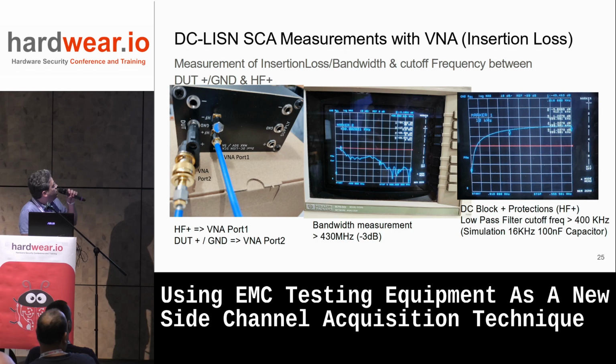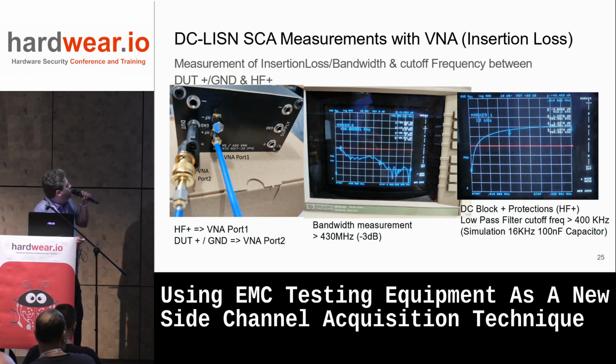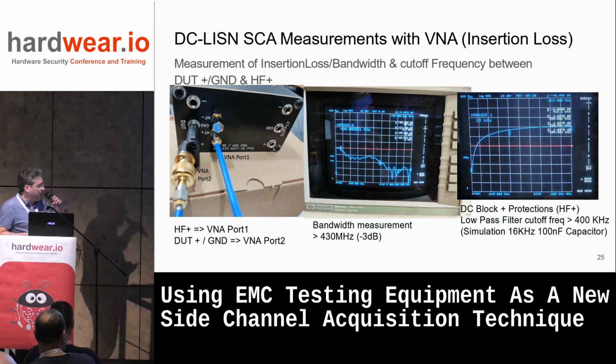And there we see the measurement, insertion bandwidths and cutoff frequency between the DUT and the HF plus. There, it's where you will do the measurement. So DUT is your device under test. And there it's where you will connect your oscilloscope. So there, we have about 400 megahertz bandwidth. So it's interesting to do side channel up to frequencies of more or less 400 megahertz.